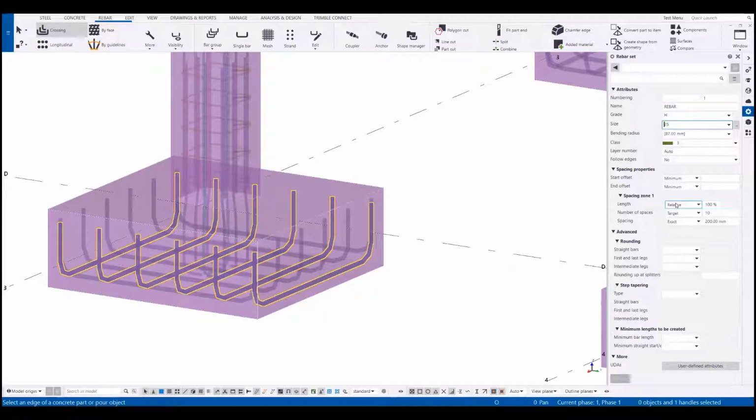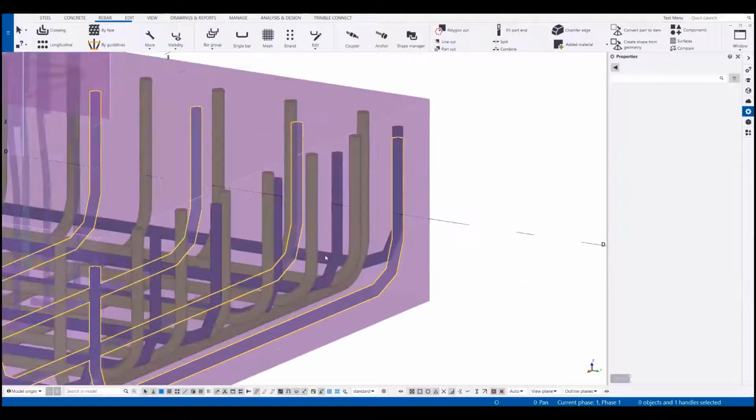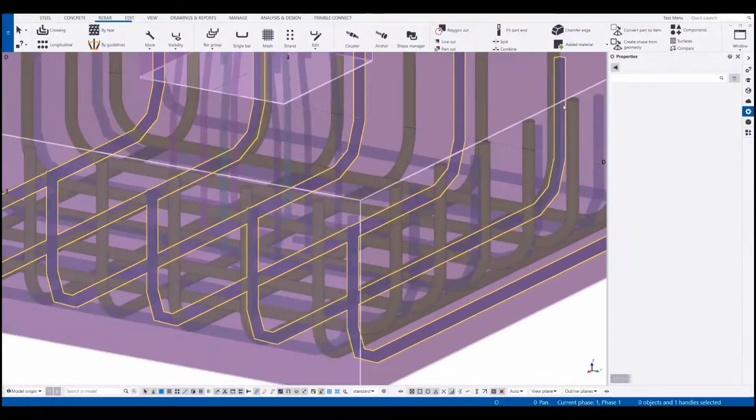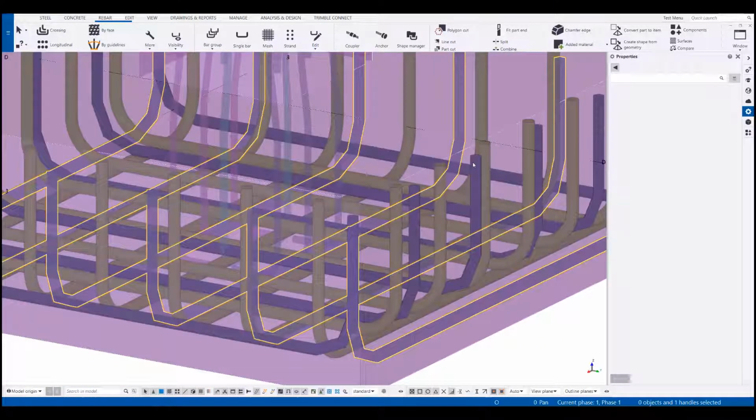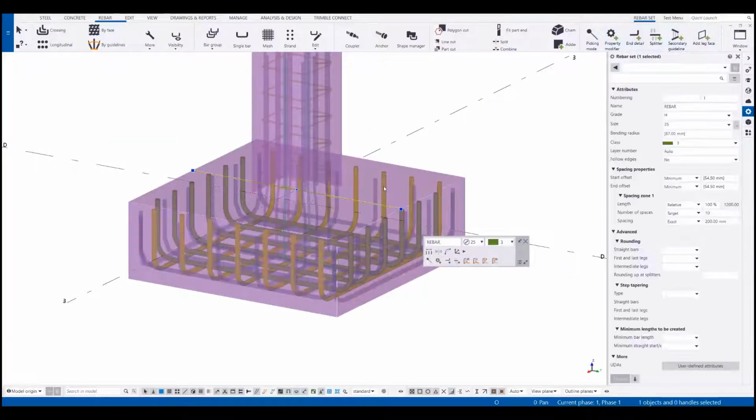Rebar sets are intelligent and understand their relativity to other objects. Reading the cover values from Tekla Structural Designer, the sets then automatically layer. Using the IFC as a reference has outstanding advantages when detailing. You can spot clashes and areas of concern well before putting mouse to model, or ensure the bars are perfectly relative to their designed counterparts. When you're done with the specific area, you can easily turn the IFC off and continue to move to other areas. You're changing the details from the original design.